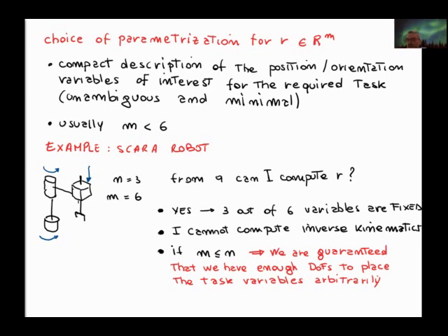But what I cannot do is the other way around, so the inverse kinematics. That means I cannot arbitrarily, given 6 arbitrary numbers for position and orientation, realize these numbers by placing the robot in a certain configuration using only 4 joints, because we cannot cover a 6D space with a 4D one. That was the thing.